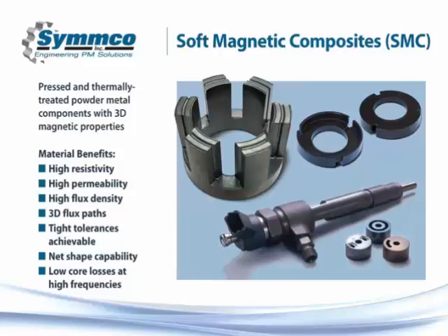It comes as a powder. It is compacted. It has a very different thermal process than typical powder metal. So I don't want anyone to think that soft magnetic sees that same 2050 degrees. It's a much different animal in the sintering world. We don't truly sinter it. It's a thermal process, and that's what supports the coating on those particles.